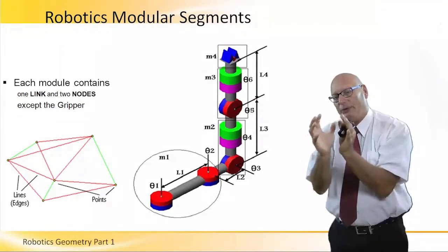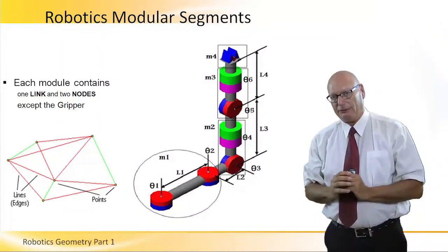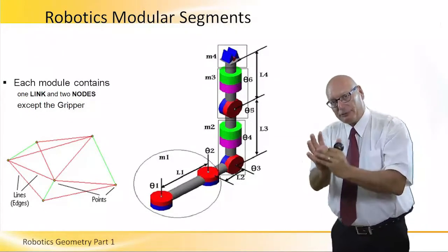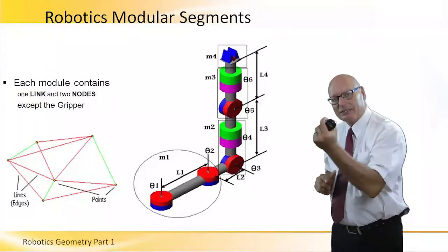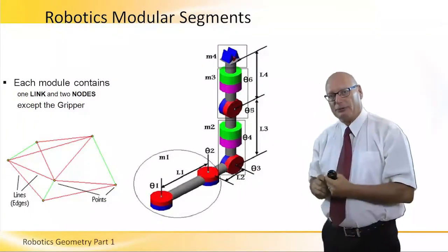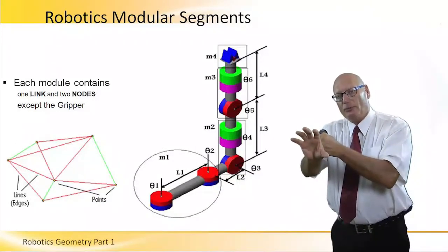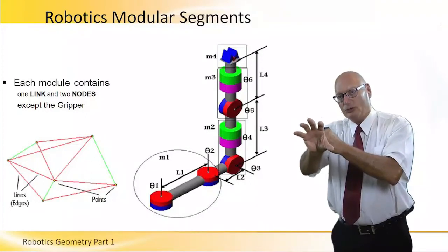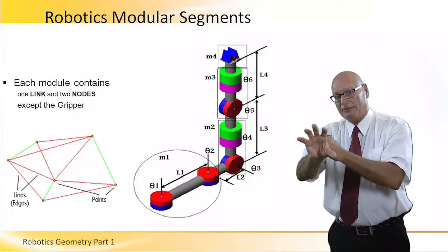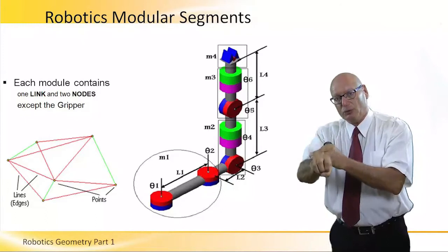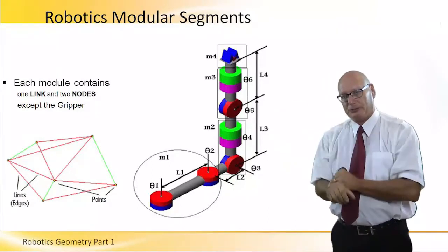That means that if we isolate the gripper from the entire robot, the center of gravity of the gripper itself, even without holding any object, is away from its own joint, which might create some problems, especially if we'd like to do a pick and place of a heavy object.